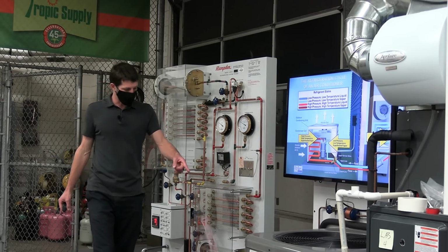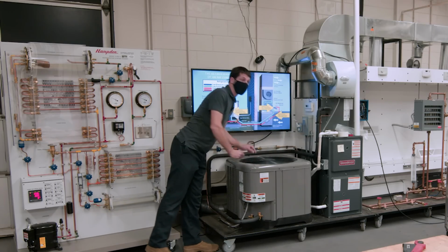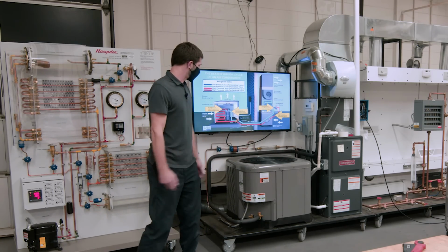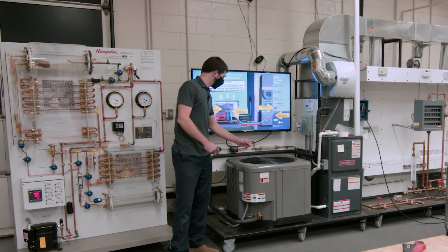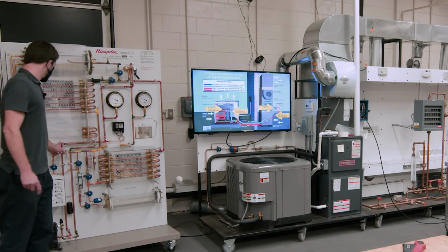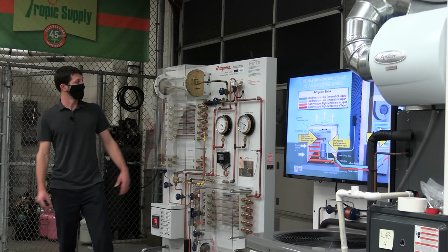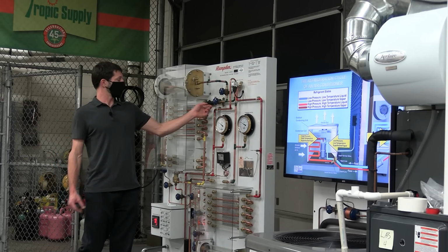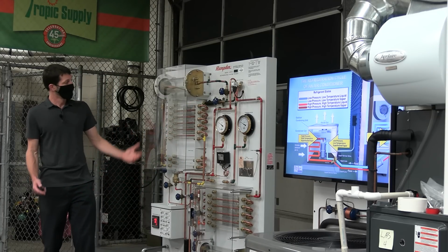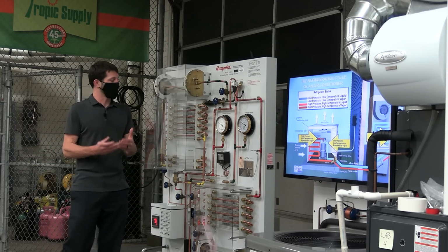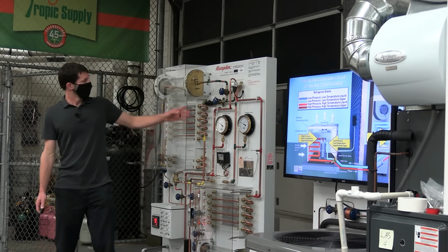And I see inside this one, we have an outdoor thermostatic expansion valve, and this one has a stainless steel head on that, and it's welded there. As well, the bulb is no longer copper, and the line is no longer copper on a lot of new systems because all that stuff breaks. It rubs, it vibrates, you lose the charge once again. This copper bulb may have got squeezed or something, and there's a problem with that. So all this stuff is now stainless steel, and stainless steel and copper work pretty good together, so you can clamp it there as well.